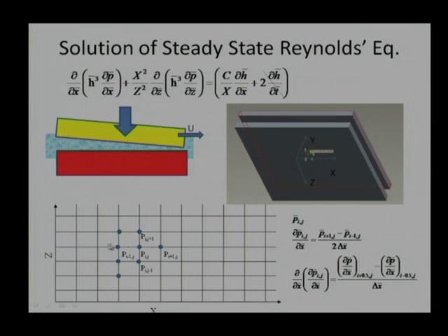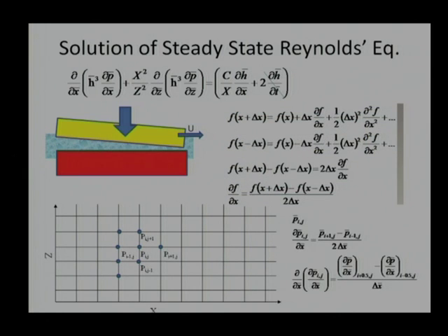And if we go for the second gradient, we are required to calculate p at the mid node, that means somewhere in between. The mid node will not be there when we implement this formula here. There will be only the nodes. So that is some sort of accuracy requirement. We can explain this with the Taylor series.